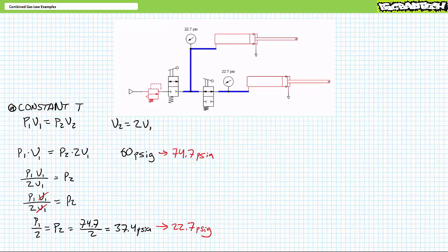Let this be a lesson about those tricky problems in textbooks and tests which feature statements like pressure doubles or temperature doubles. Using the absolute scale as one must when employing the combined gas laws, 50 psi gauge is not half as much pressure as 100 psi gauge, nor is 80 degrees Fahrenheit twice as hot as 40 degrees Fahrenheit. If a problem doesn't specify absolute or gauge, seek clarification from your instructor.